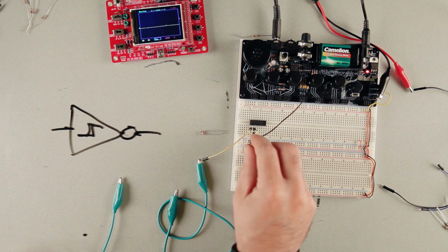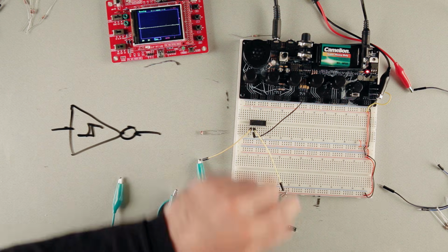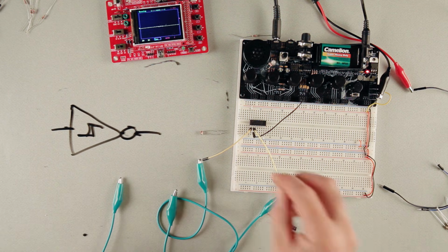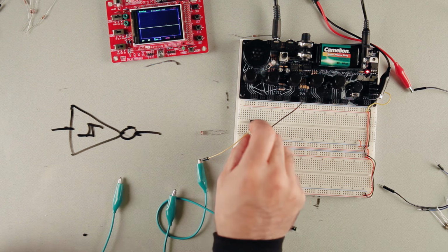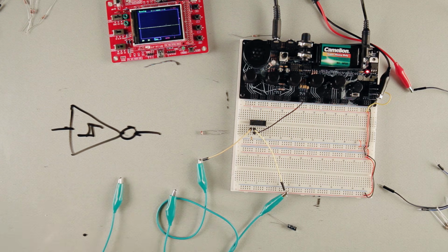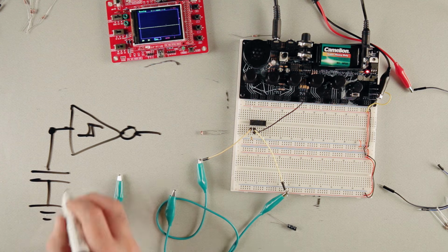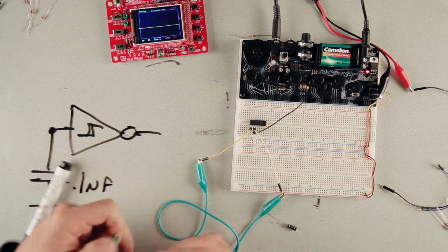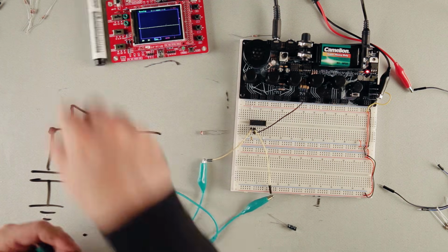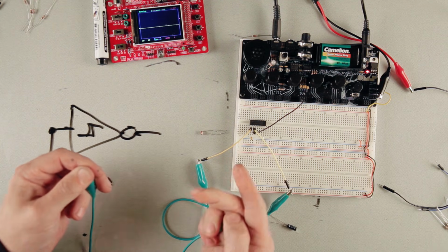Well, as I was saying before, we can change the capacitor. So I'm going to take out this 1 microfarad capacitor, and now I'm going to put in a 0.1 microfarad. So let's plug that in. So that's between the input and ground. I'm putting this capacitor. This is a 0.1 now. And I'm going to turn the volume up. And when I touch this, you can hear the pitch going up and down.